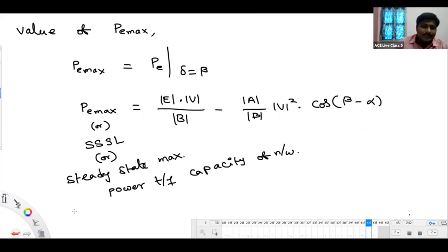Why it is so, listen here, Gopiraju. Generally, whatever parameter B we have taken here is representing the series impedance of the network. Even though you consider the shunt element or neglect the shunt element, I'm saying it again, it may not show a great effect on the maximum power transfer value. That's why we are neglecting the shunt elements. All of you understood the statement I said?